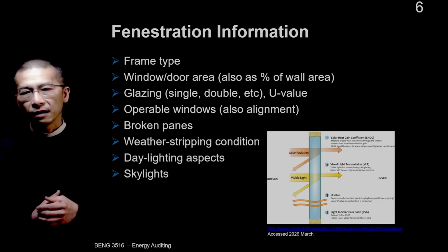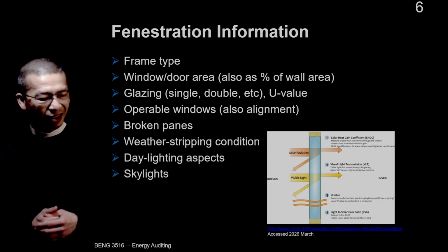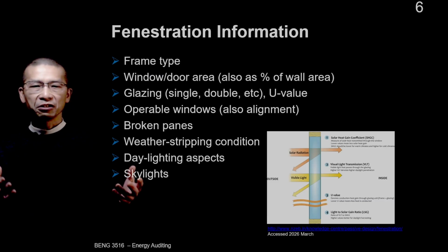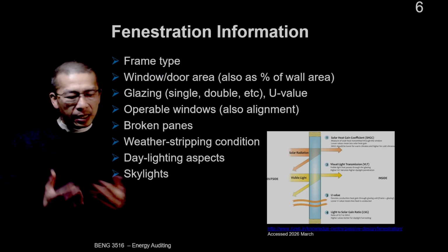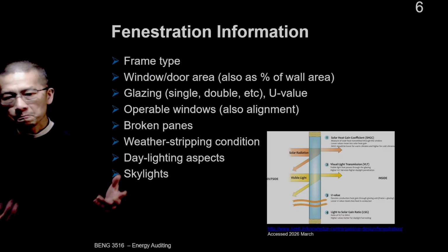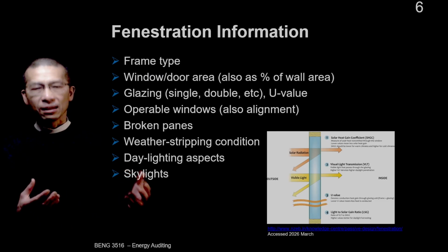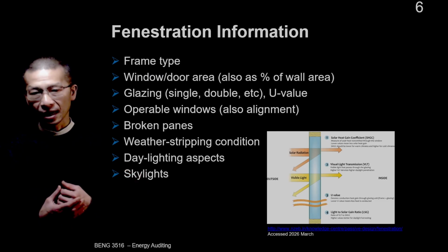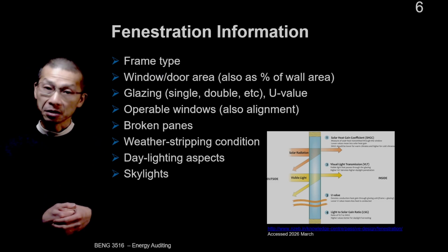Daylighting. If a building has many windows or skylights, can we turn the lights off during the day? Maybe we can save on lighting, but skylights might increase our solar heat gain and increase the cooling cost during the summertime, right?